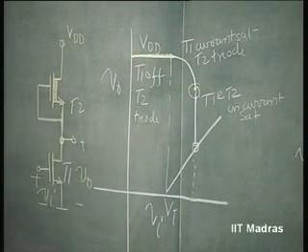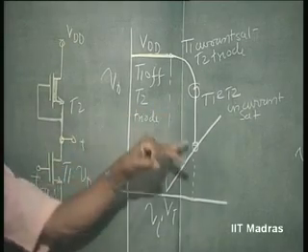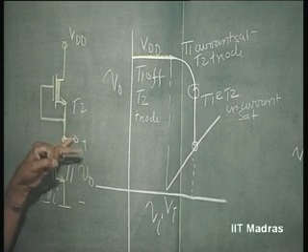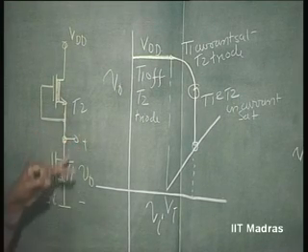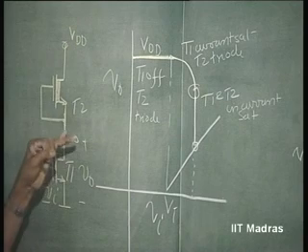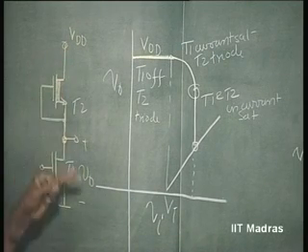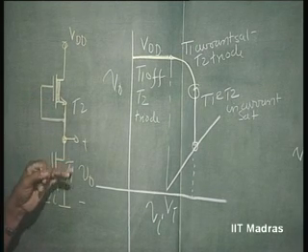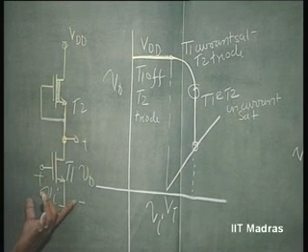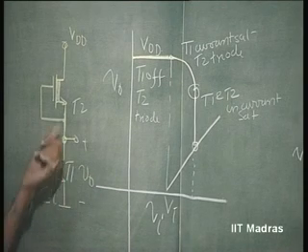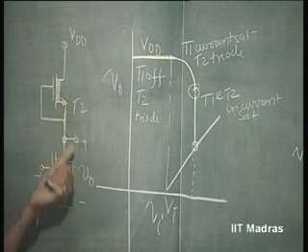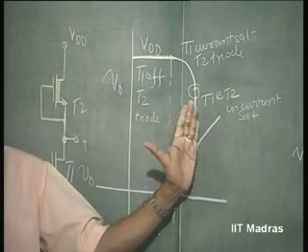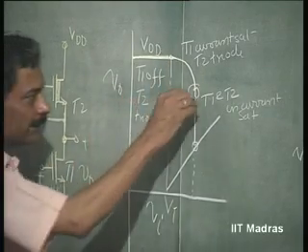Now, in actual practice obviously gain is not infinity, because when each of these FETs enters current saturation region, there will be this RDS of each of these FETs, RDS1 and RDS2, coming into picture. So, RDS1 parallel RDS2 into GM of the FET is the actual gain. Under this case, when we have assumed that these are ideal current sources and sinks, the gain looks to be infinity. So, this is that region.